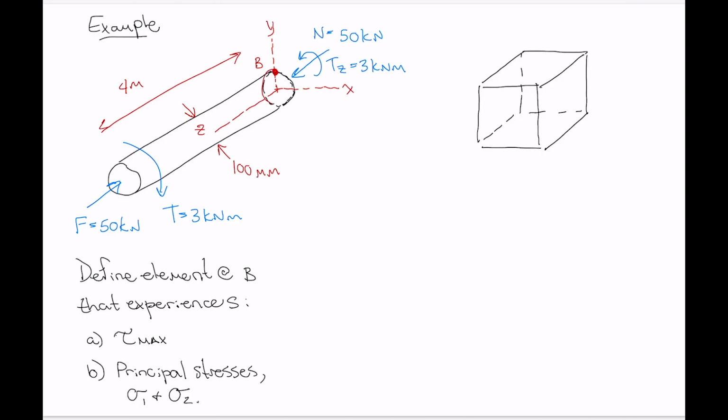So our section plane, right, is the back face there. And that is the back face of that volumetric element that's in the section plane, and the rest of that element is projecting into the body of the rod down the z-axis. Worth redrawing our coordinate system, just so we don't make a mistake here.